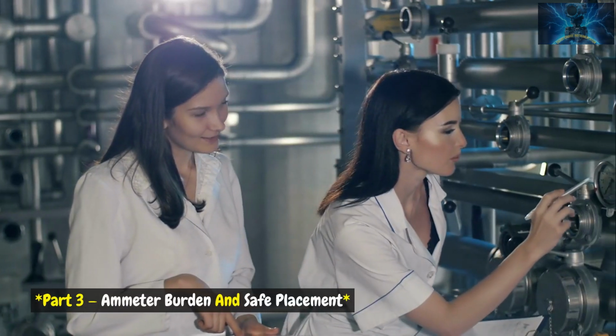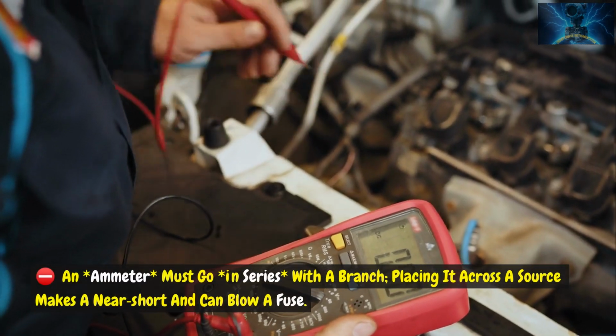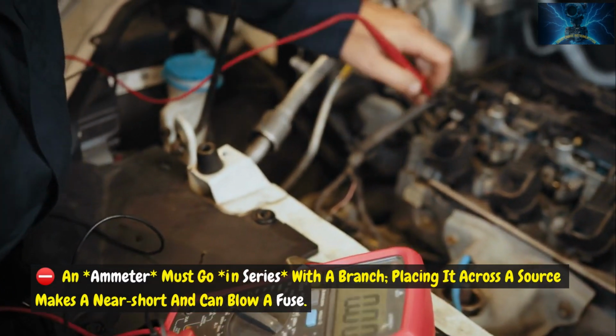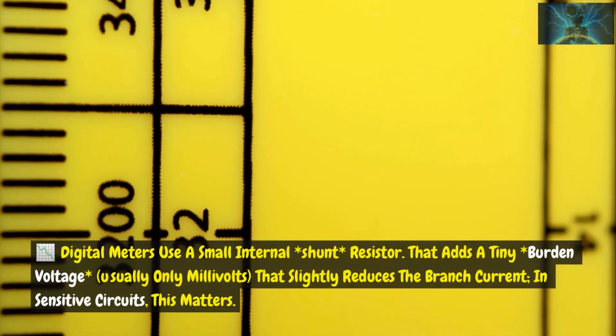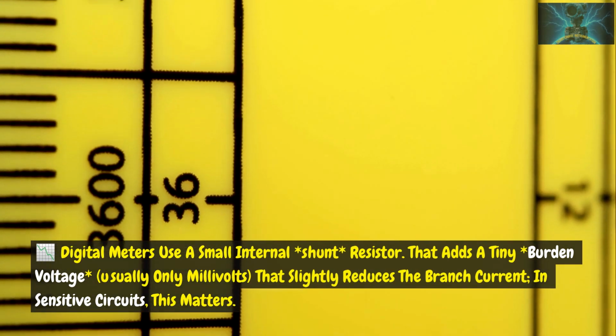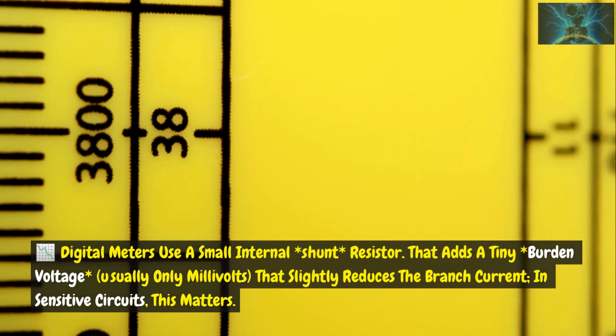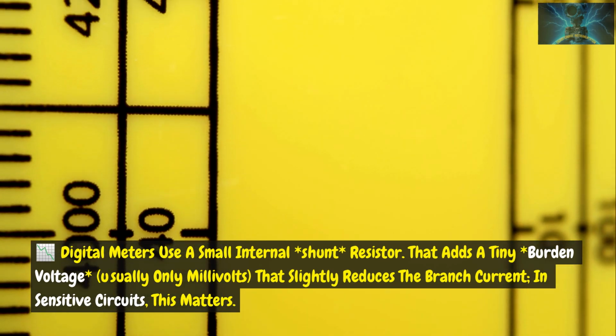Part 3. Ammeter burden and safe placement. An ammeter must go in series with a branch. Placing it across a source makes a near short and can blow a fuse. Digital meters use a small internal shunt resistor that adds a tiny burden voltage, usually only millivolts, that slightly reduces the branch current. In sensitive circuits, this matters.